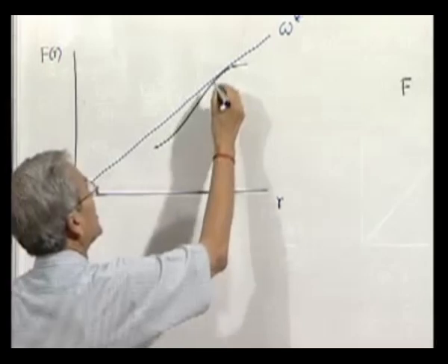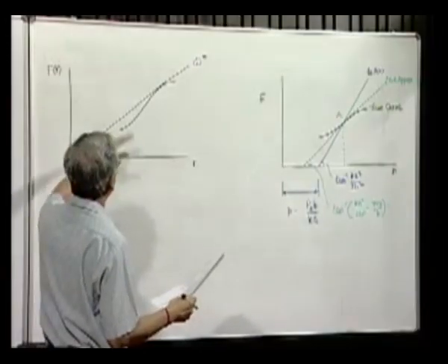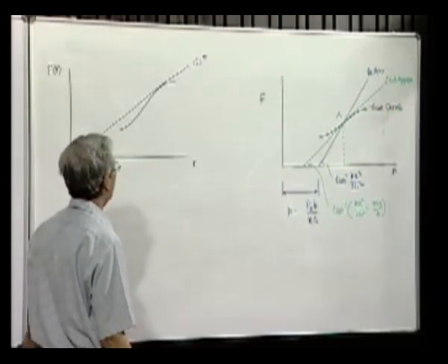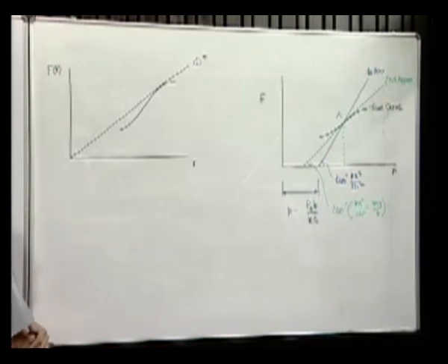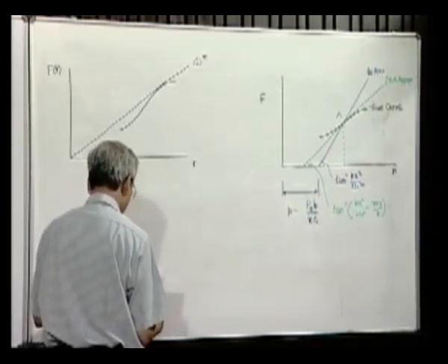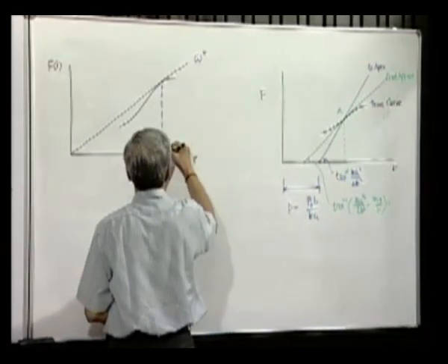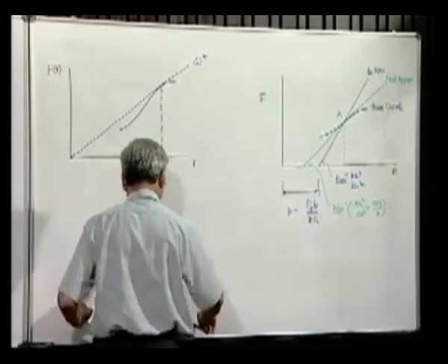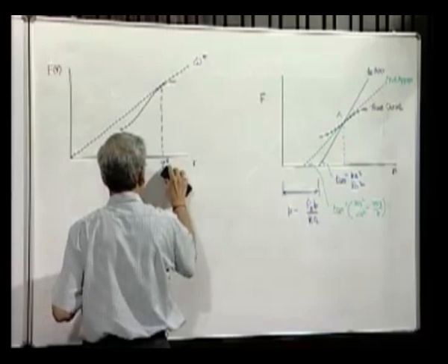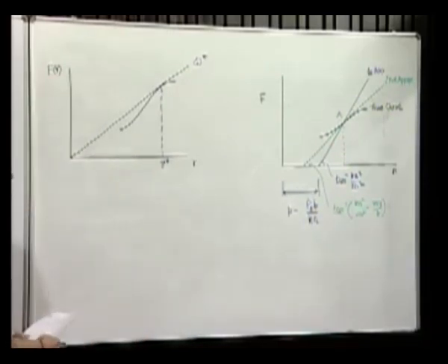So it is obvious that this is the speed at the operation has to be, to have any equilibrium operation, the speed has to be below this, because otherwise Fr can never be equal to the centrifugal force, as you can see that. And it is also very clear from this that this is the critical R or radius of operation beyond which the operation is unstable.